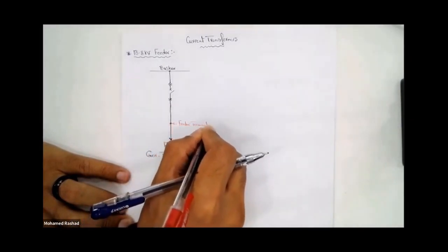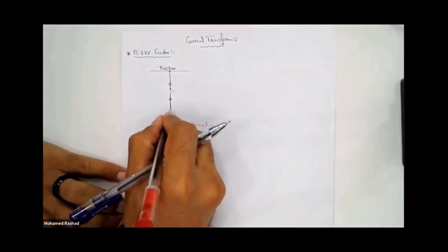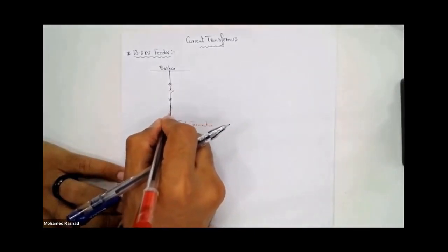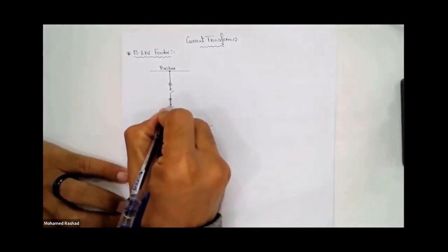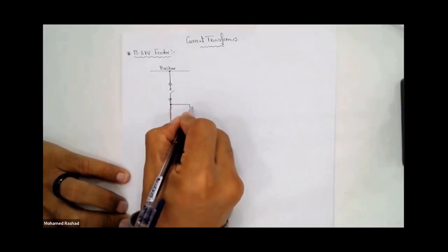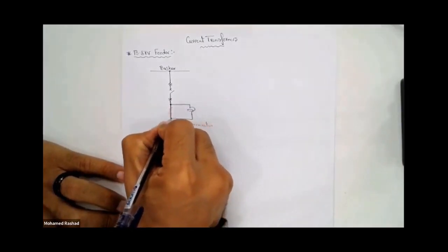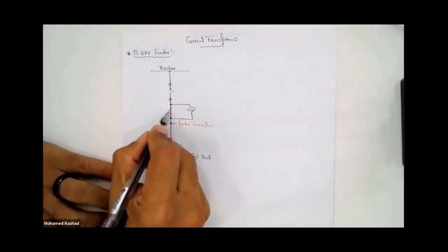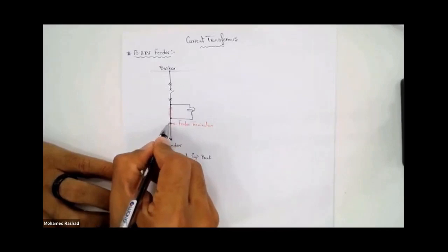These are the terminals where my cable connects. So before these terminals, I come and, for example, remove this part like this, and then I start to connect my current transformer here in its place. So for example, my primary is usually just one turn. So I have removed this part and installed the current transformer in its place.